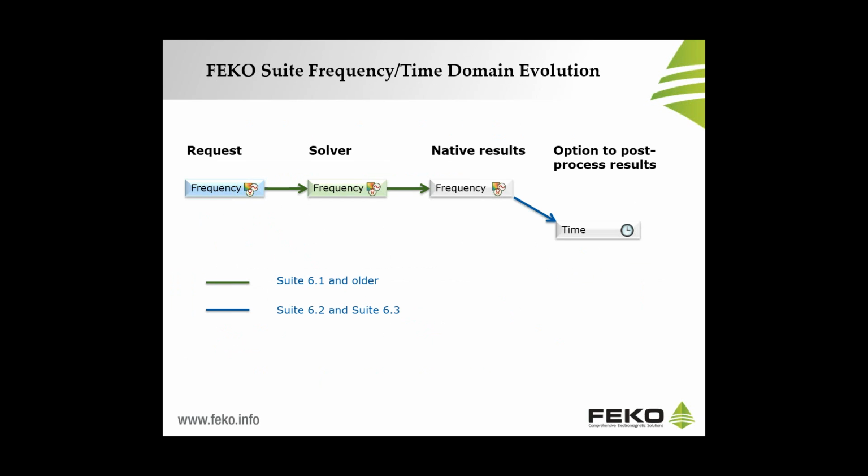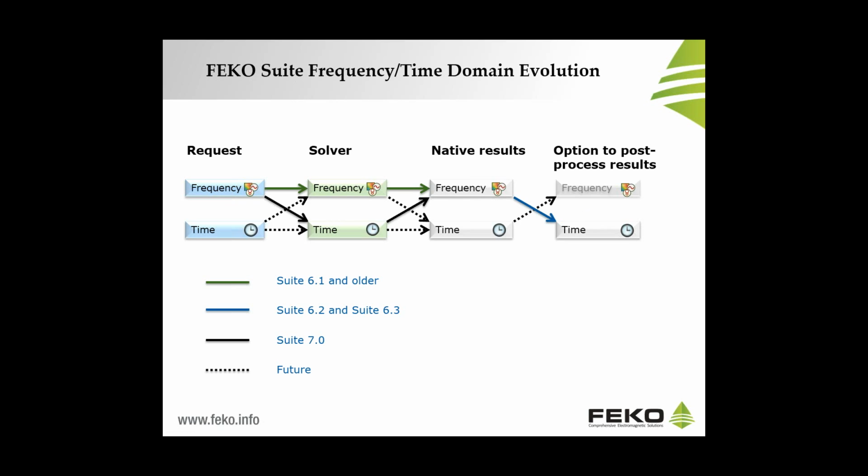In FEKO Suite 7.0, we are adding, as you can see now, the possibility to perform time domain analysis in a way that the user needs to make a request on the frequency domain, enable and launch the time domain solver, get the results on the frequency domain, and with the possibility to show the results on the time domain via post-processing in FEKO.